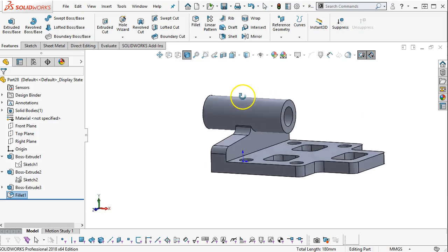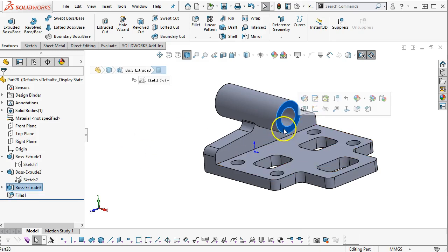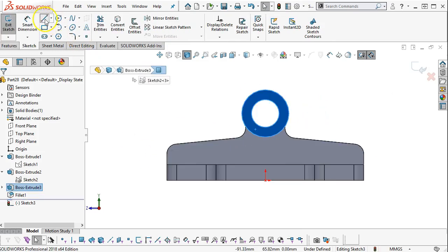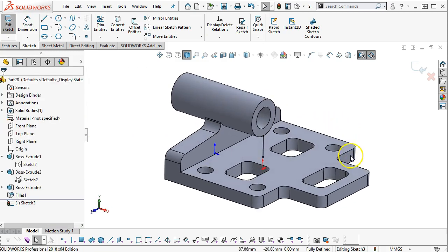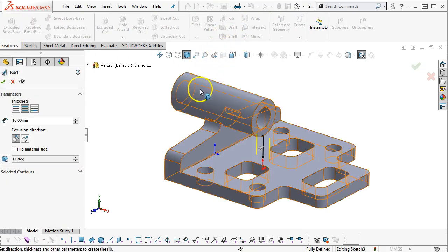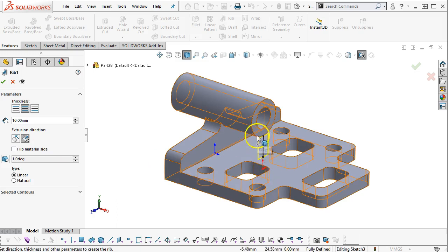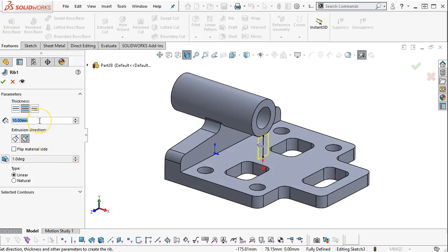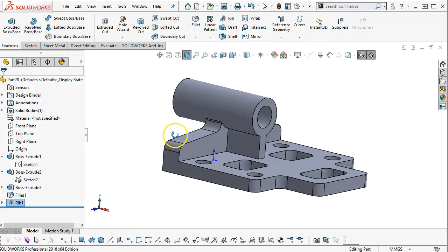All right, so I mentioned the rib back to this geometry. If I were to open up a sketch, I just want to try this real quick. And we'll go with quadrant to the edge. Go into features, set the rib. So don't like the direction. Problem always exists with this curvature. Is it going to cooperate? And let's just go with a 6 millimeter rib. Direction is okay. And it finds the intersection and builds up the geometry. So that all looks good.